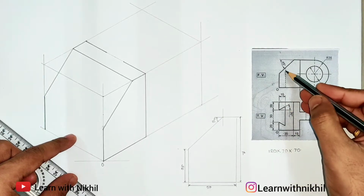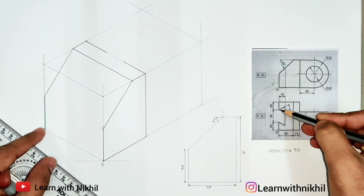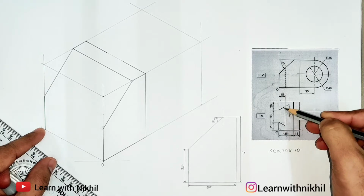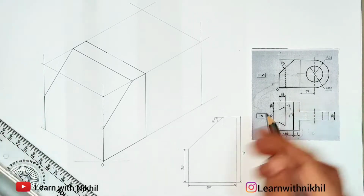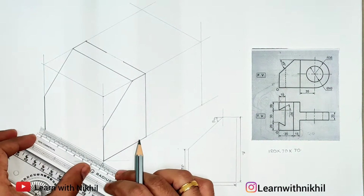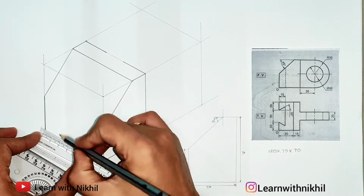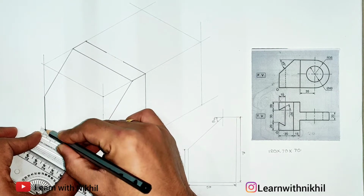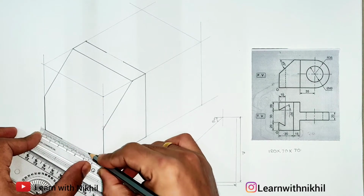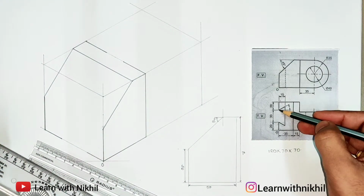Now here, as you can see, it is a drilled part from top to bottom. This distance given is 20-20, and then you have again an angle of 30 degrees. This also you have to plot the same way as we did earlier for the 45 degree. I'll show you. First I'll mark this dimension. This is 20. This is 20. And the center part blank is 30.